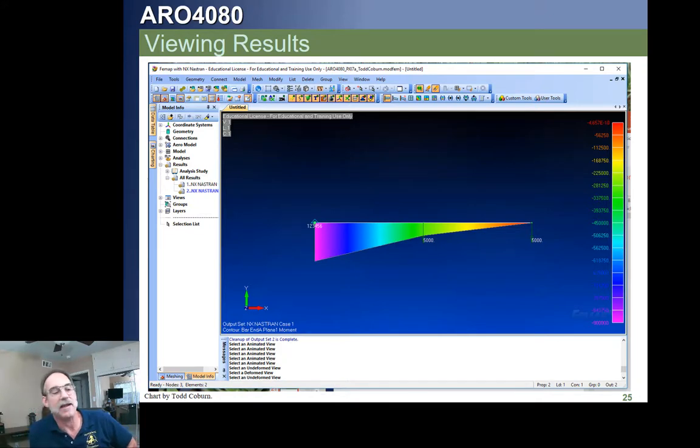Now this is just beam elements, but we can do the same thing later when we're making frame models with a floor beam, showing the bending moment diagrams and the shear diagrams on those elements. It'll make it really quick to see what spots in our model are maximum, so we can do hand analysis to determine if our model is good. This is very good for showing visual loads, it is very impressive.